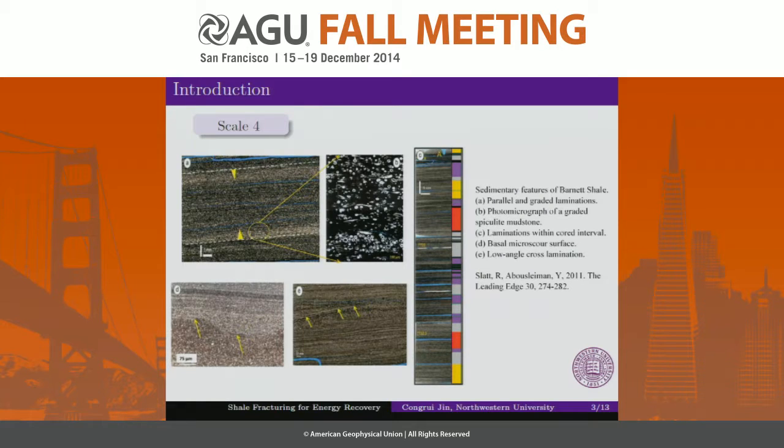As a result of sediment transport by a variety of processes, many shale specimens exhibit millimeter and centimeter scale grain size variability, laminations, bedding planes, scour surfaces, and burrows, which all contribute to shale geomechanical characteristics such as the degree of anisotropy, tensile strength, and fracture toughness. The light objects, about 60 microns in typical size, are silt inclusions randomly distributed throughout the composite.